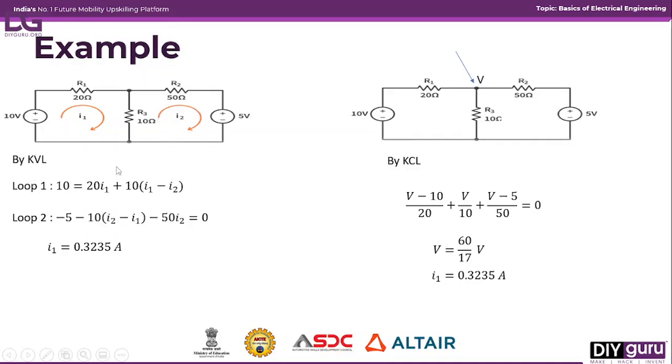So in this loop 2 will give you this direction. This is the direct current direction we have applied. You just take the KVL also in the same direction, so the leaving current polarity we will write. If you apply the KVL in this fashion, first we will get -5 plus minus, because current always enters at the positive terminal and leaves at the negative terminal, minus.